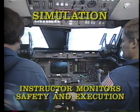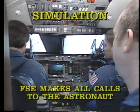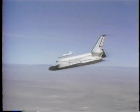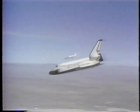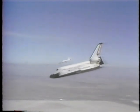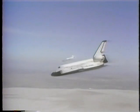During the simulation, the instructor monitors the overall safety and execution of the approach, while the FSE makes all calls to the astronaut. In order to better understand how the STA simulates the orbiter's approach, let's look at an actual shuttle descent. The approach begins as a steep dive. Flying at 290 knots, the orbiter descends along a 17 to 19 degree angle at a rate of approximately 15,000 feet per minute. Its target is a point 7,500 feet short of the runway.